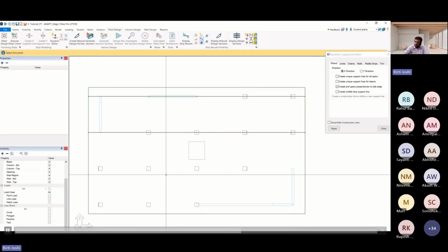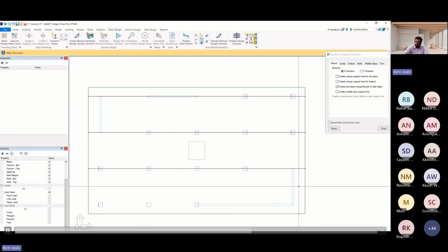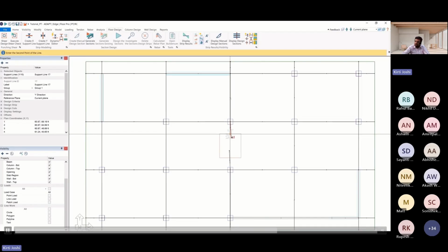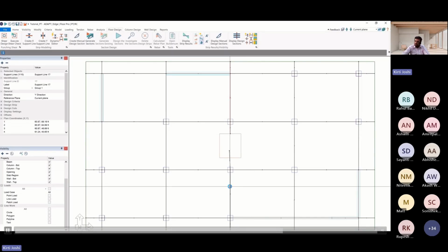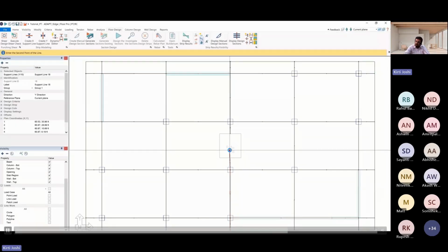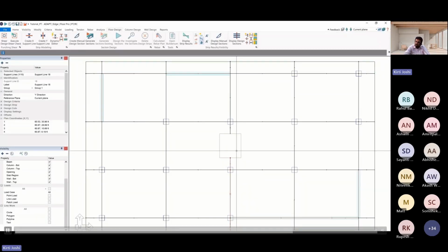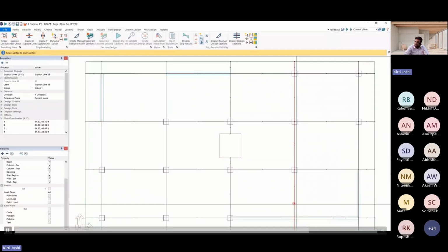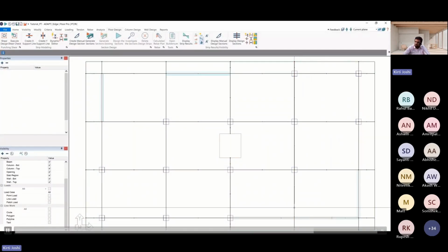Like you can draw the second and the third X direction support line. And also you can draw similarly, as you can see on the screen, in the Y directions. The next is we'll start modifying the two support lines that are at the openings, you can see, so that the support line is snapped to the edge of the opening. Then after we can add a vertex where the support line crosses the beams, as this beam is acting over the support, as you can see.